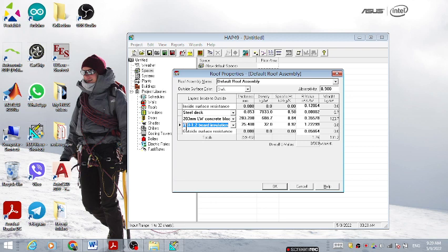It's RSI 1.0. You need to use your actual build-up or insulation, tiles, whatever types. You can write here tiles, and you can enter the thickness, the density, the factors, coefficients. So you will be able to get the exact value of U, the overall heat transfer coefficient. Okay, so you can correct this. All of them you can override and input your correct data.